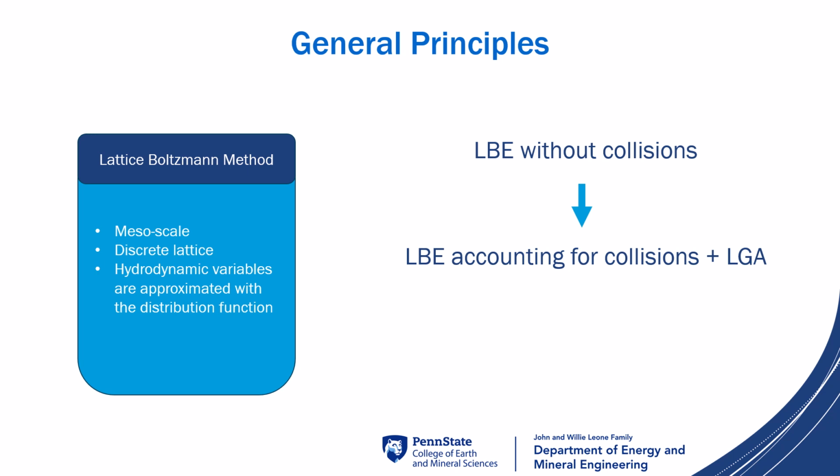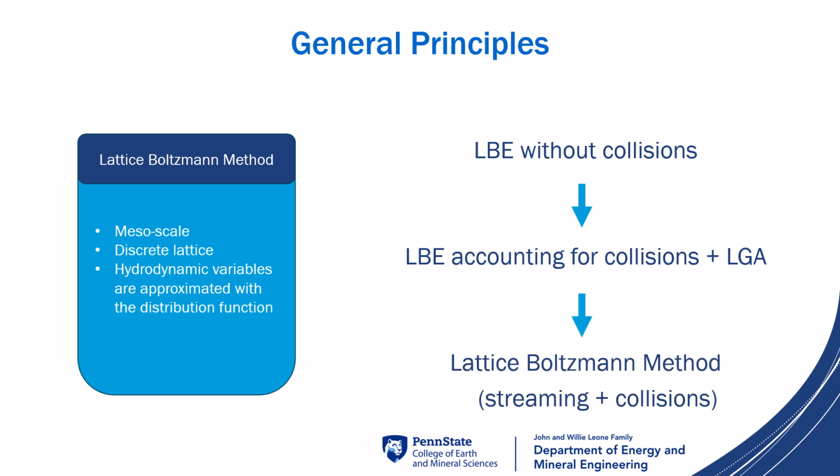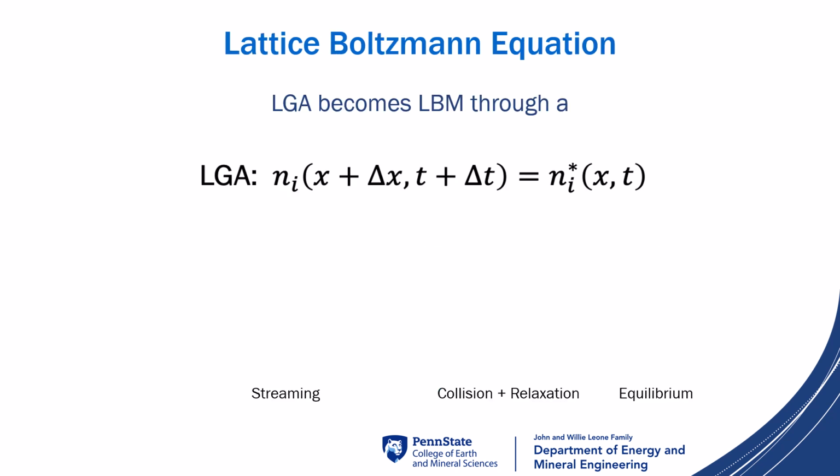Collisions between these distributions enable momentum exchange, pressure propagation, and shear, while also conserving mass and momentum locally. In essence, the Lattice-Boltzmann method models how many particles are moving in each direction at each point in space. These distributions evolve through two main steps, streaming and collision. When implemented properly, this bottom-up statistical approach can effectively reproduce the behavior of real fluids.